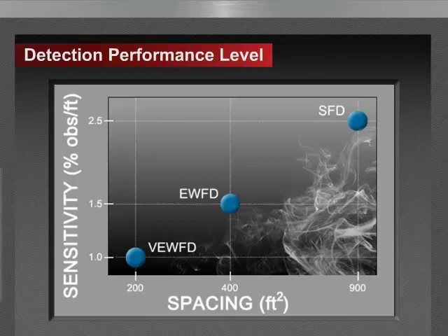So increasing placement density and sensitivity improves the chance of detecting incipient low-energy fires, again, before fire conditions threaten services and network reliability.